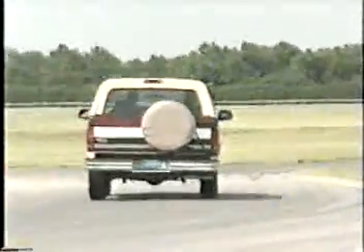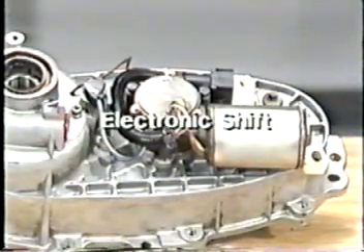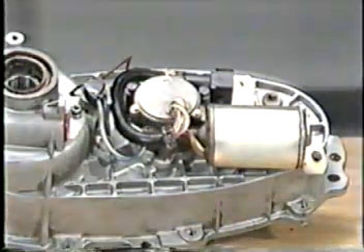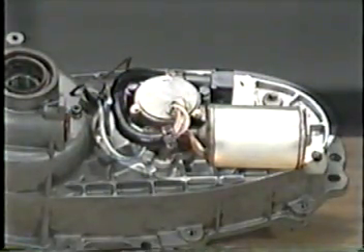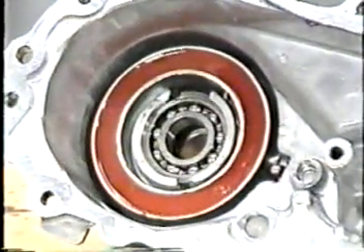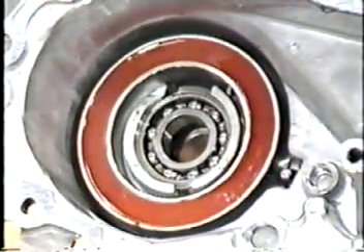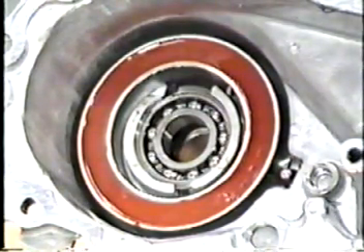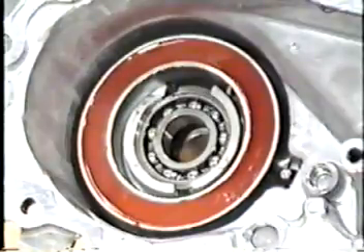Some vehicles are equipped with an electronic shift transfer case. Working with an electronic shift transfer case is basically the same as working with the manual version, except for an externally mounted shift motor. The shift motor is operated by an electronic control module that has self-test capabilities. Inside the transfer case is a magnetic clutch similar to an air conditioning compressor clutch. It spins up the front drive system to vehicle speed in milliseconds. This allows the shift between 2 high and 4 high to be made at normal off-road driving speed.